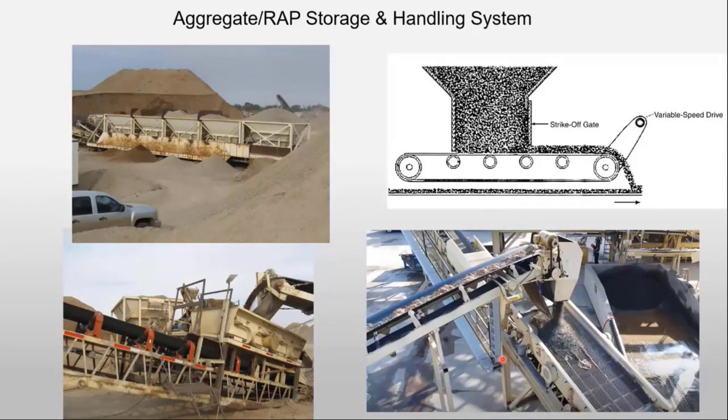Every one of those bins you see at the top left has something like a schematic like this underneath it, and it's depositing on a conveyor at a certain rate. If it's 20%, 15%, 20%, whatever it is, they have to gauge that. It all has to be calibrated to make sure that it puts out the right amount. There's also moisture. What complicates it a lot is the fact that there's moisture in all this, so that has to be allowed for.